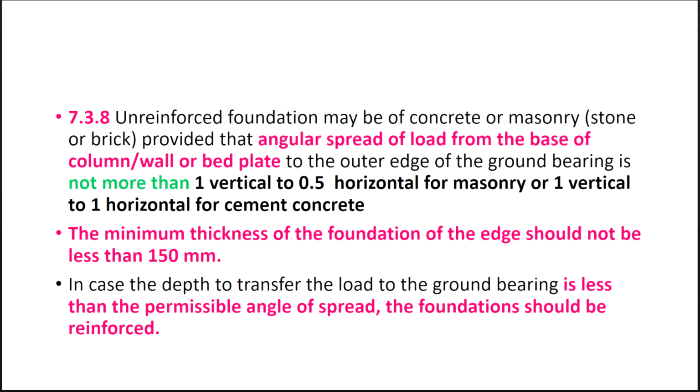कैसे करते हैं? आपने कहीं सुना भी होगा, कहीं देखा भी होगा. What we are doing? कहीं मूरम डाल देते हैं. We do the ramming of that मूरम. We do some rubble soling also, so that we increase the bearing capacity of that particular strata. करते कि नहीं करते हैं? Yes, sir. We are trying to increase the bearing capacity of that particular soil by putting either muram or some type of a boulder filling.